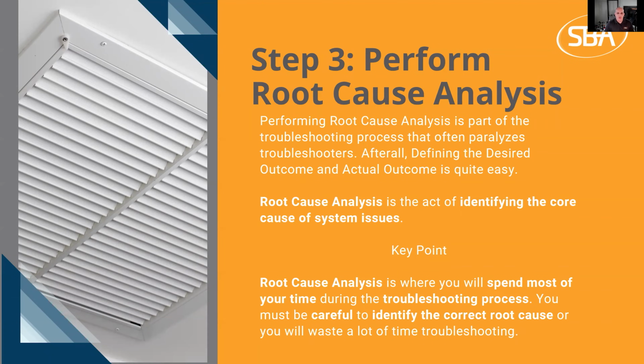So for example, you've got a data center, the BAS server should be up, but the BAS server is intermittently down. We asked one of our 5 questions around frequency. We determined that the server goes down at the same time. We went and checked the trunk link. We realized that there's a massive database upload going on in the data center at that time on the same trunk link as the BAS traffic. And the quality of service is taking down the BAS server, so the server's going down, and we've identified the root cause. That's the thought process you have when you're identifying. I mean, that's very much simplified, but that's the approach you take.